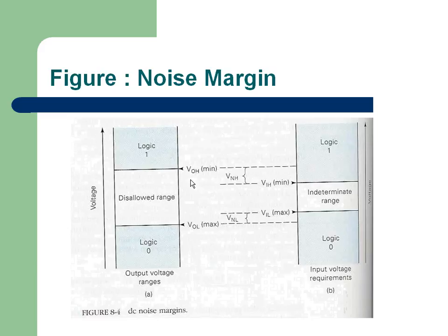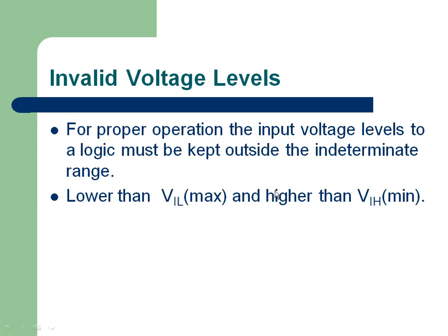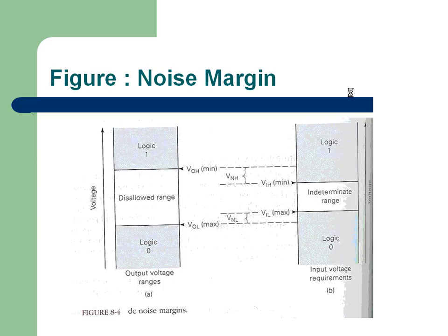But again, yesterday I was trying to show an example of fan-out, how many gates can be connected. When the device is going close to the maximum fan-out, the output voltage level won't be the optimal voltage level. There will be variation. That is why the precise terminology uses maximum and minimum. Anything in this zone is the invalid, indeterminate zone.